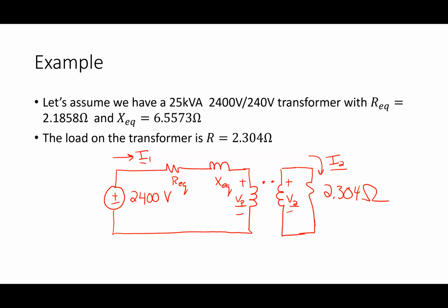One thing I said last time is what's true about this impedance over here, this load that I put on here. What can I do with that load? How can I treat that load in my analysis? I can reflect that across to the primary. I talked about this last time. If I have a transformer, here's V1, here's I1, and here's a load on this side, Z load. Here's V2, here's I2.